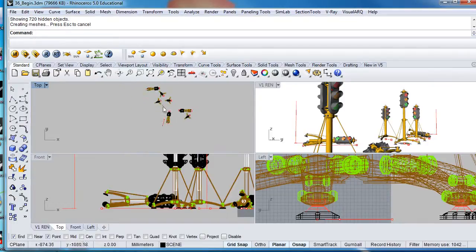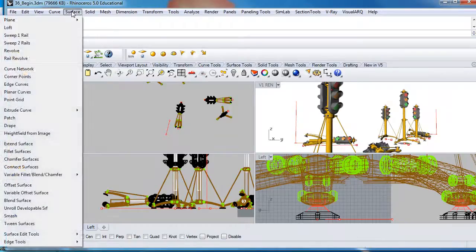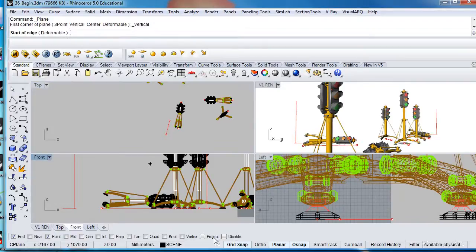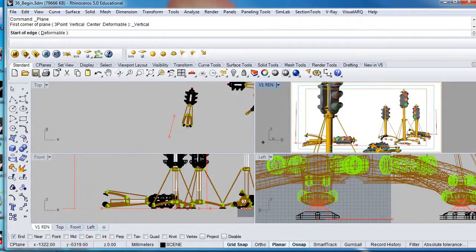you'll notice that there's just two items that were left there before, which are going to be the locations of our figures in space. So that's where they're going to sit in space. The command we're going to use in order to create those surfaces is the surface plane vertical command. Make sure that the endpoint is the only one that's activated in terms of the snaps command, and we'll simply move on to the correct layer.